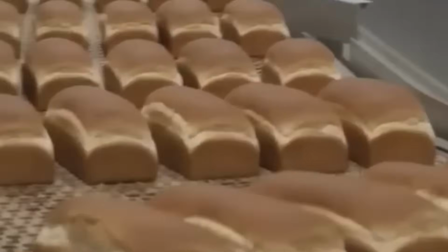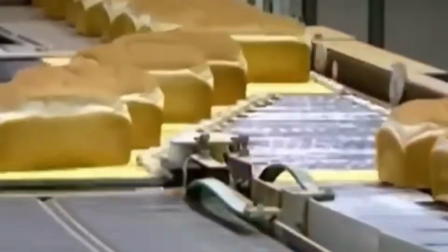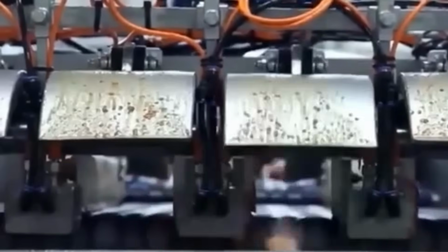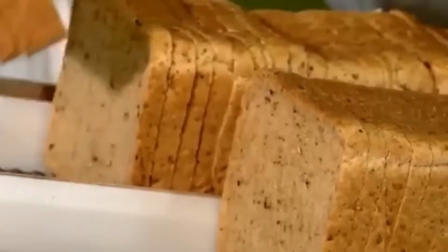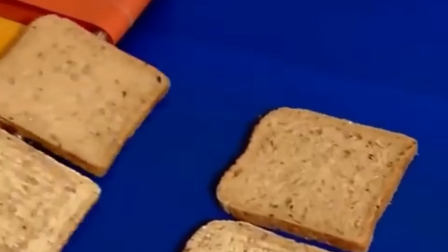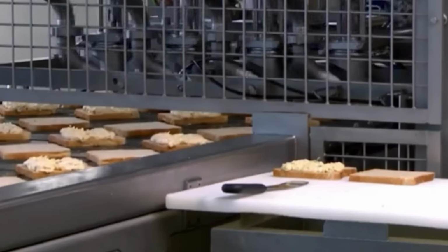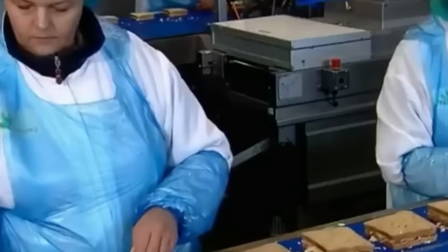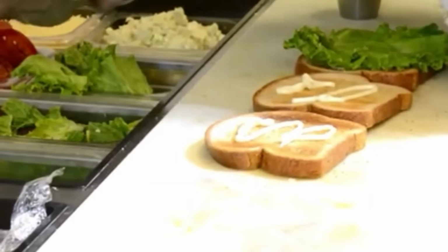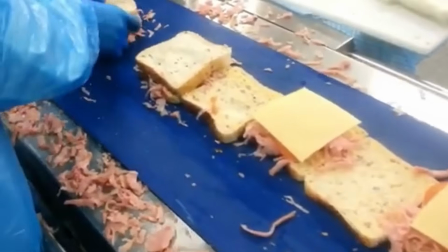It starts with bread loaves, already baked, cooled, and brought into the slicing system in racks, where they are automatically depanned, aligned, and fed into high-speed slicers fitted with ultra-sharp, serrated, or ultrasonic blades that oscillate thousands of times per second to deliver uniform, clean-edge slices without compressing the soft interior crumb or fracturing the crust.